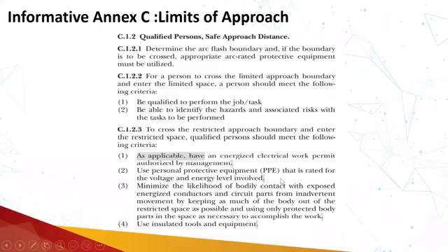He will be wearing personal protective equipment for the voltage and energy level involved. Minimize the likelihood of bodily contact with exposed energized conductors and circuit parts from inadvertent movement by keeping as much of the body out of the restricted space as possible, and using only protected body parts in the space necessary to accomplish those works.